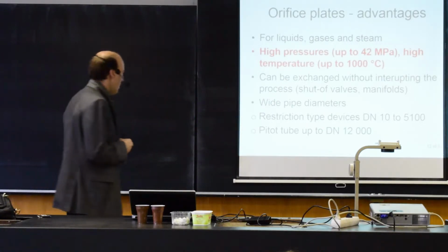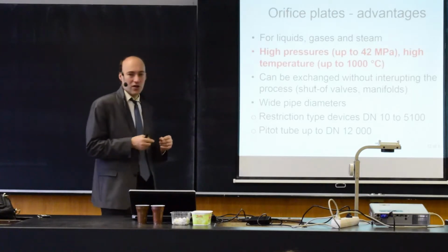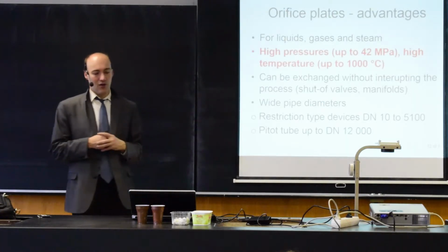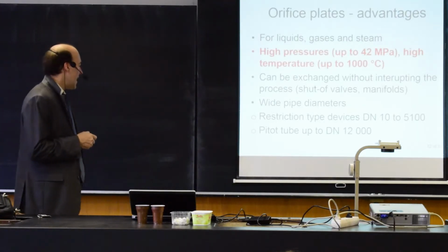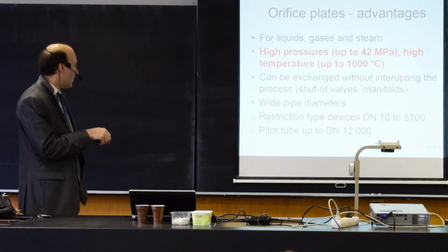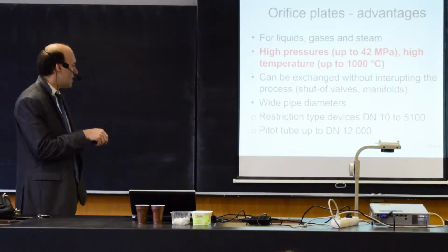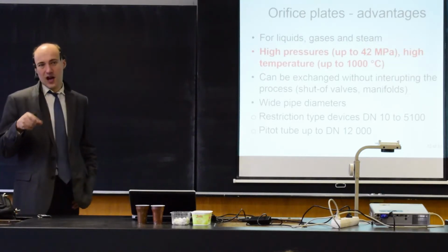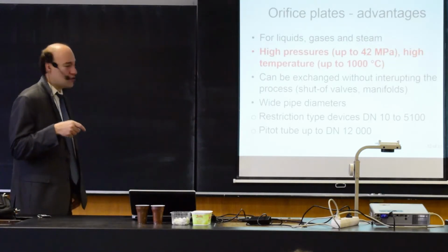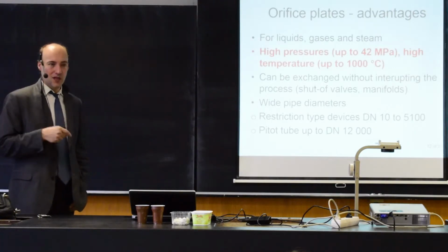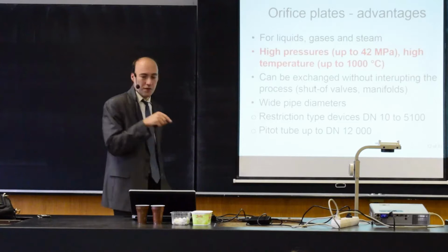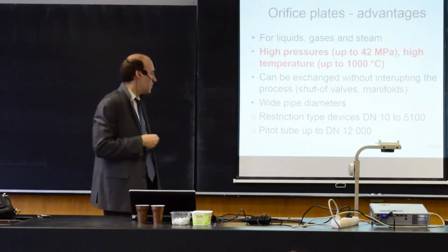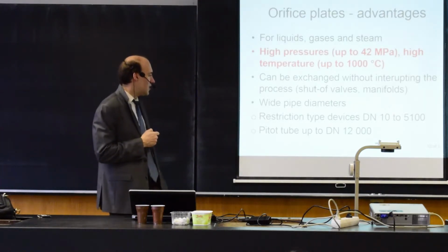If your pipe has a small diameter, you can use a similar orifice plate, but it's not defined in the standard. And you can use it for those diameters, so it works from diameter 10 millimeters up to more than 5 meters. The standards are not from 10 but from 50 millimeters, but it works also from 10 millimeters.